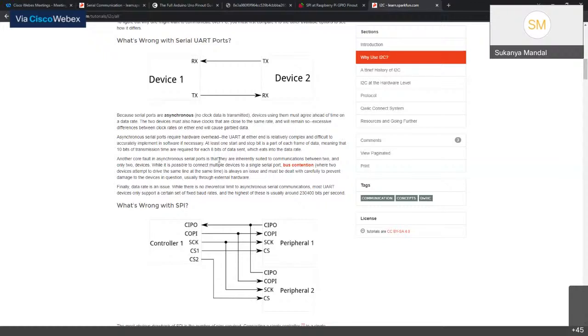Now this is about memory consumption. In UART we saw every piece of data is transmitted with 8 bits, but it also has an additional 2 bits for every data that is transferred. So let's say you transfer Hello World. Each of these characters comprises 8 bits. Now add 2 more bits to each of them. That increases the data size and hence the transmission size when it comes to larger data.